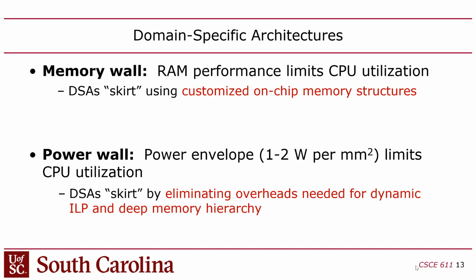And the other problem is that because CPUs are general purpose, even without these, you can't utilize the whole thing. If you've got, for example, floating point units on the CPU and you're running integer code, the floating point units are wasted. They're not used. They just sit there idle, right? Likewise, if you're doing floating point code, you've got spare integer units that aren't doing anything. So a domain-specific architecture, because it's designed for a specific application, you can boost the utilization of the hardware, because you can only put in there what you actually need for the application. So if you're doing a neural processor for doing animojis, obviously you're not going to waste hardware with things that aren't required to run an animoji. So you get higher utilization and thus higher performance and higher power efficiency. That's why these specialized processors are needed in order to be able to unlock these new applications.